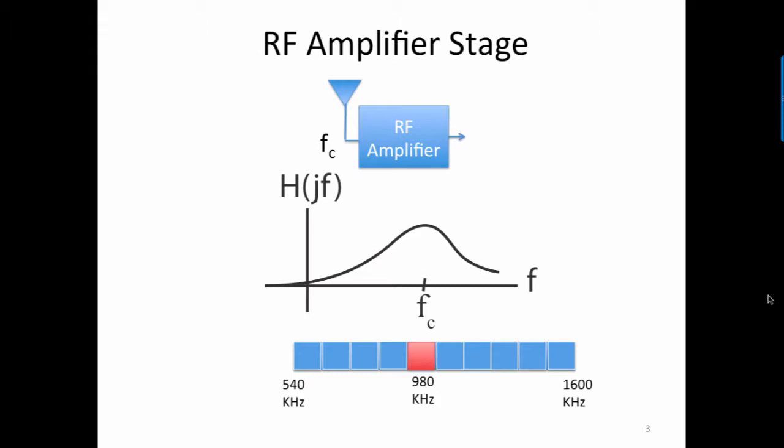The RF amplifier is a variable tuned amplifier. When a station is tuned in, the center frequency of the tuned amplifier is adjusted to the carrier frequency, FC, by tuning one of the elements, like a capacitor. This allows for maximum gain of the amplifier to be at the carrier frequency. The RF amplifier is not a selective amplifier, so it also passes adjacent channels in addition to FC. This is a potential problem that we will discuss shortly.